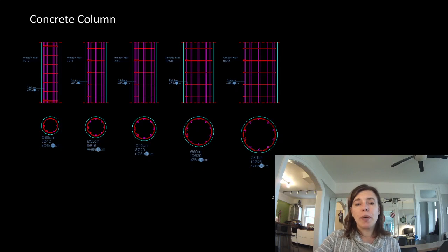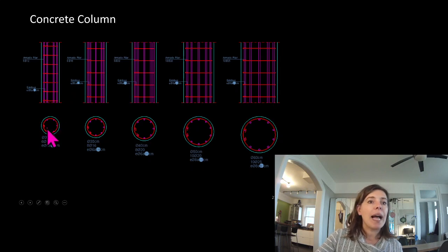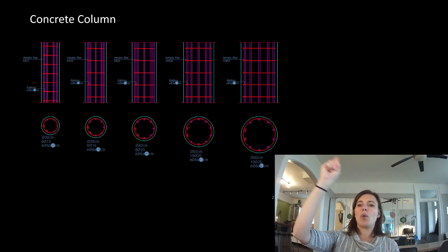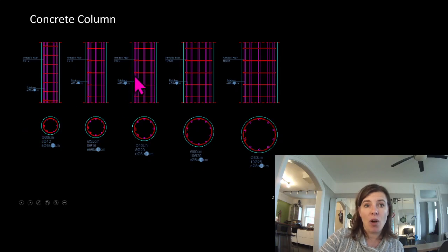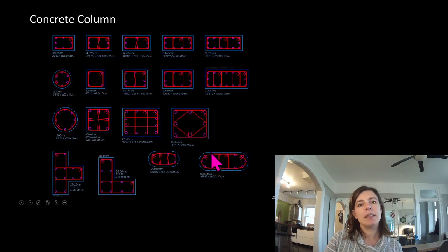Round columns, if you're doing maybe a Sonotube, for example, or a caisson, would often be round, or you might do a building with a round column. Again, we have closed ties. They might spiral the ties, so it goes around like that, with the spacing between the spiral being the spacing that we would have called up in these ties. You can have funky shapes in your columns as well, but we just have to make sure we've closed this in some way that encloses our loads to stop the concrete from popping out.